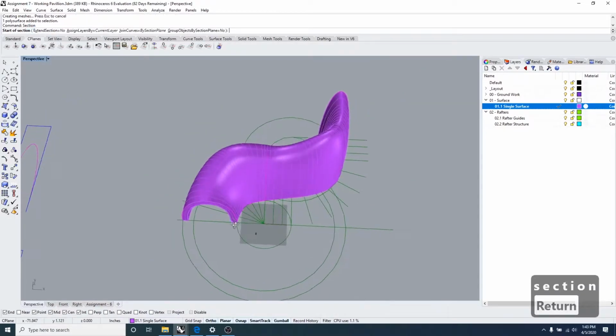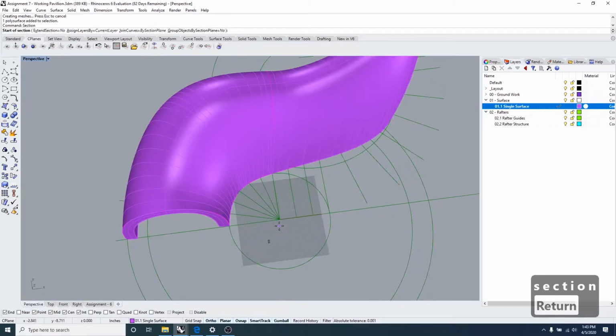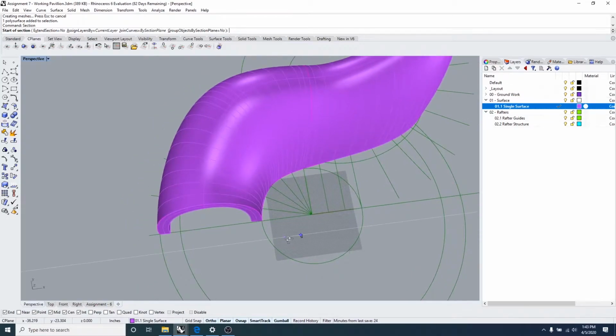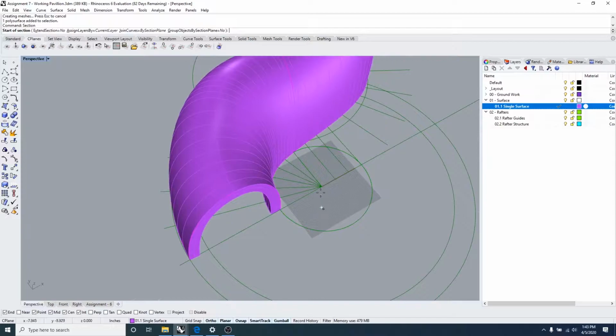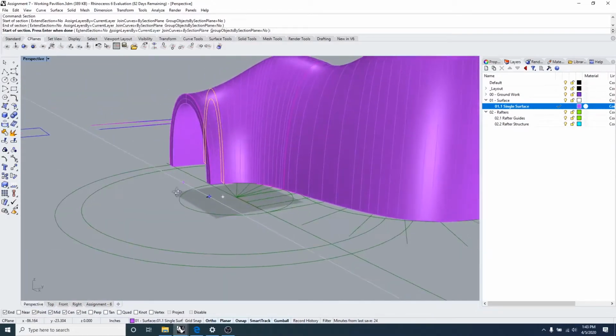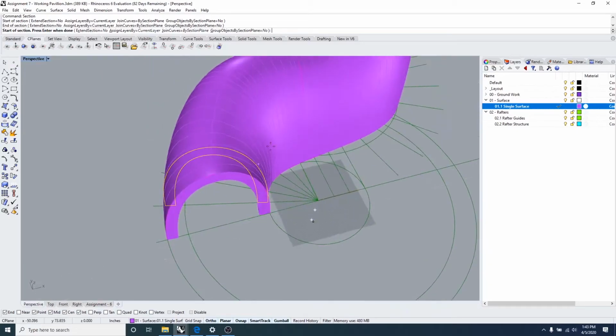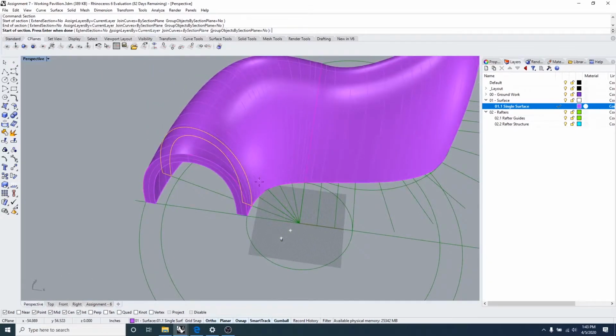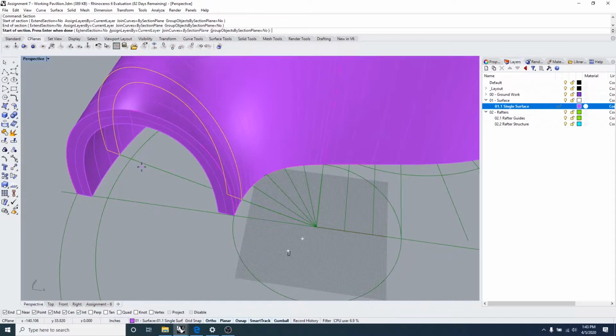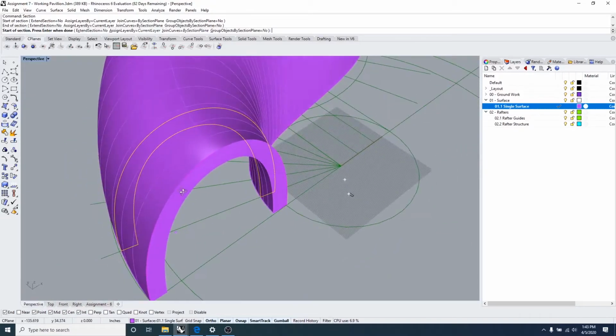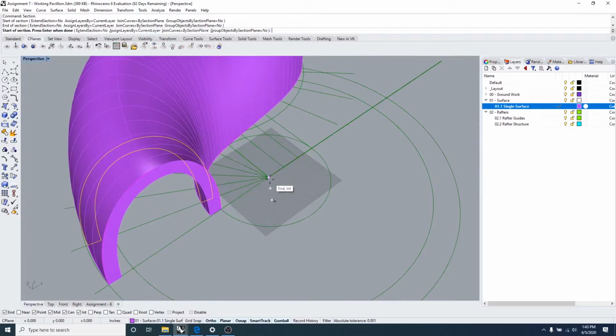What that's going to do, it's going to create a section between the two given points. And those two given points are going to be driven by you. Notice that Rhino is asking for a point for a start section. So we're going to click this point, and then end of section is going to be this one here. Notice how it's actually doing a profile at that intersection between the thickened surface and the grid line that we have running below here from our previous assignment, the groundwork.